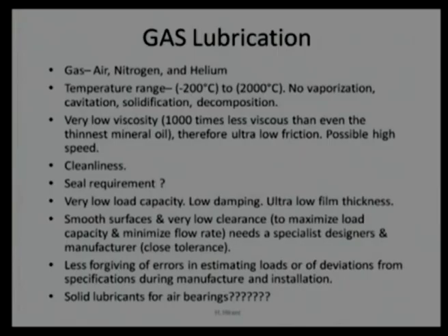These bearings are highly optimized. Once we have a thorough understanding of the complete system, load, speed, temperature, variation in the load, variation in the speed, then only should we utilize air bearings. Talk about the rheometer, where we want to find out the actual measuring torque, the torque resistance given by the fluid. We require extremely good bearings. In those situations, these air bearings can be utilized.